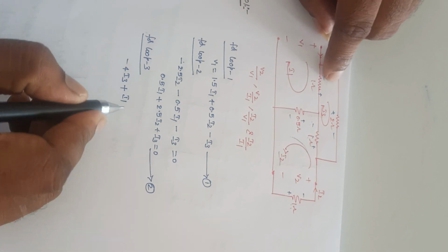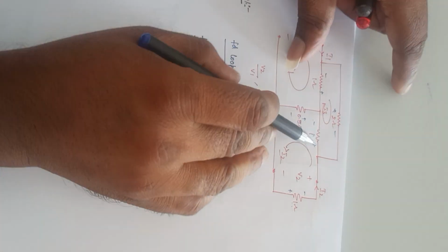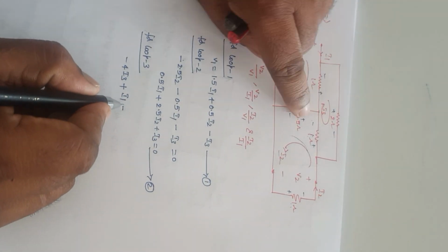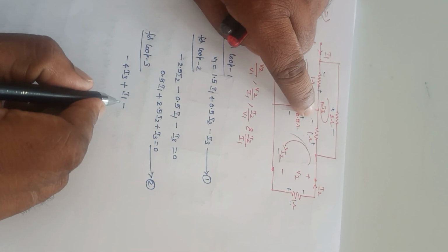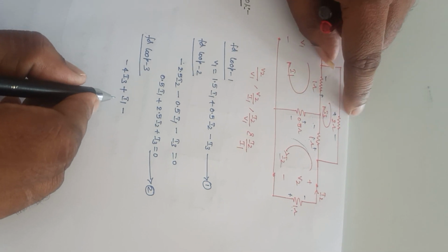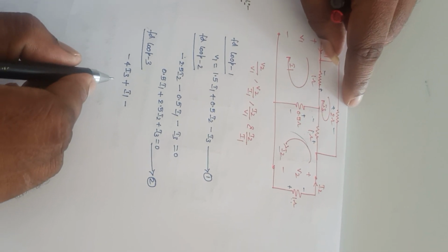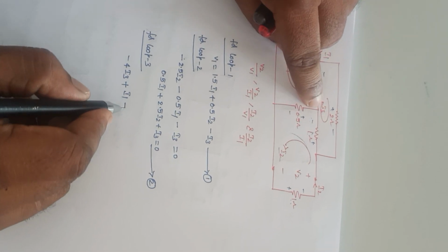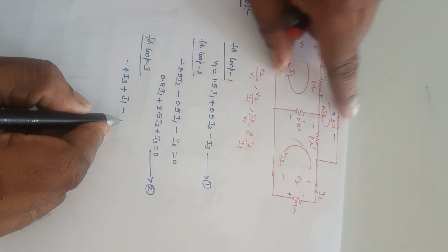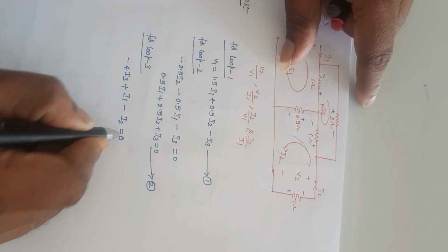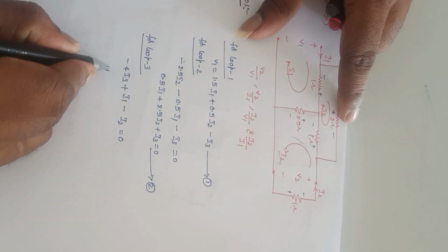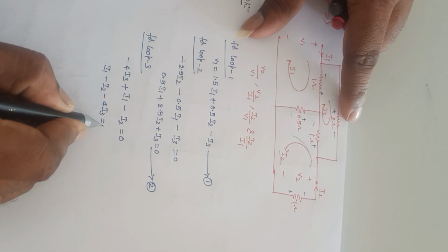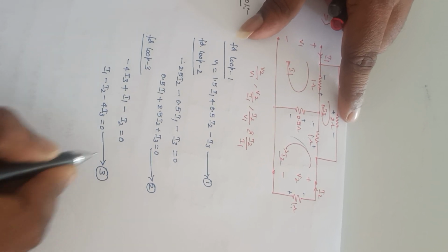I1 into 1, this I1. But in this resistor, this I3 and this I2 both are in the same direction, so it is minus. If I take the current leaving terminal as reference here, minus I2 into 1, that is equal to 0. So if I rewrite this expression, I1 minus I2 minus 4 I3 is equal to 0. So it is equation number 3.